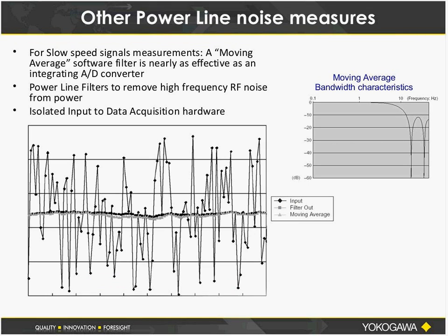If you don't have control over the device and are not able to change it to one of those, an equivalent method of accomplishing this is by using a moving average filter. A moving average filter is the same concept, but it's usually applied in firmware or in software. If you set a moving average with an integration period equal to the power line period, you'll discover it also has a notch filter at that frequency and its multiples, or harmonics.